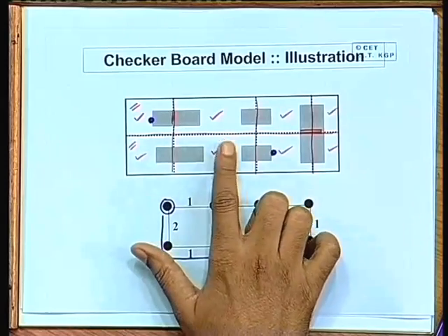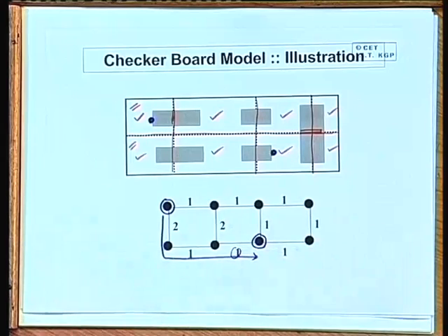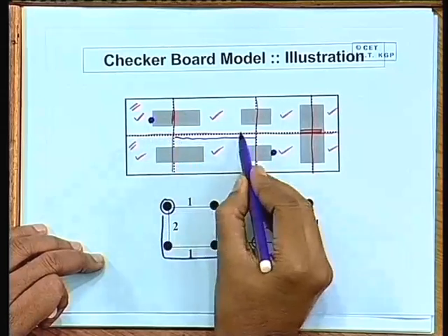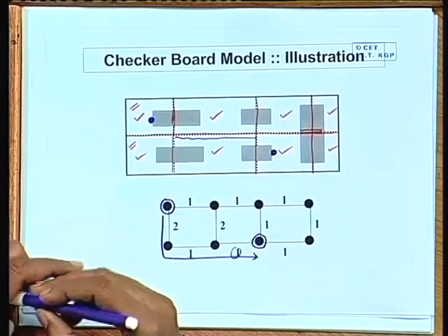there we talk about channels and switch boxes, typically channels. But in this kind of a graph, we are not really using a channel as a basic primitive, because if you look at some of the boundaries, say this boundary will be spanning several different channels. So, it would be better in terms of our future processing if we can have a data structure where the channels are individually identifiable. The next data structure does just that.